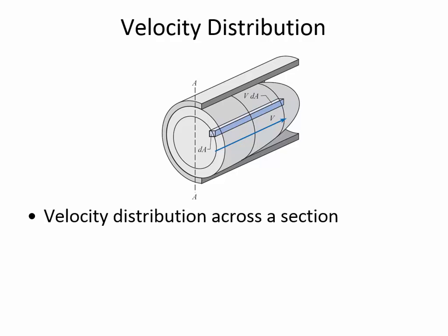And so this is a parabolic velocity distribution, but now think in 3 dimensions. This isn't just a 2-dimensional system. This is showing that in 3 dimensions you have a center where the velocity is going very quickly, and then all around the outside casing of the pipe, the velocity is reduced.